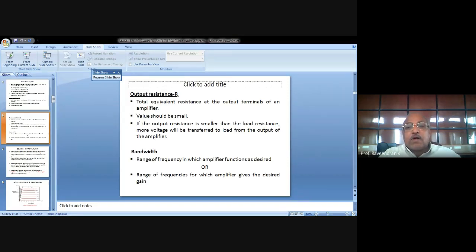So that is why it is called ICO, or sometimes in some books you can see it is ICEO, in order to symbolize it as the collector emitter configuration current with base open. That is ICEO. Okay. So ICO or ICEO. That is relatively constant, so that the variation of IB must always be independent of ICO, beta, and VBE.